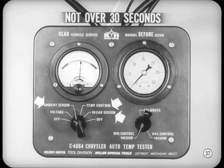Incidentally, Jack, when you're testing the sensors and selector, don't leave the dial in any of the 3 test positions for more than 30 seconds. If you do, you're liable to ruin a good sensor or selector.